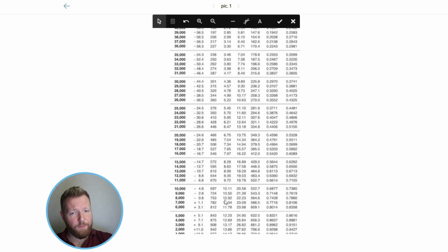So 10.92 minus 4.5 gives us 6.42. That means that we must find the pressure altitude with a corresponding psi not lower than 6.42. Going slightly up, we can find that 6.47, which corresponds to 21,000 feet, is the last acceptable psi.